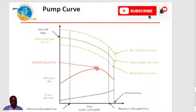Now on the opposite side, as the flow is increasing and the pump gets to its maximum flow, what do you think happens? From the behavior of the centrifugal pump with respect to the pump curve, it is going to produce minimum head at the maximum flow. The centrifugal pump will produce minimum head at the maximum flow.